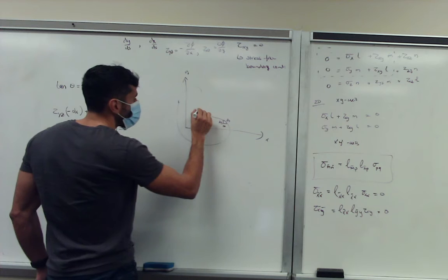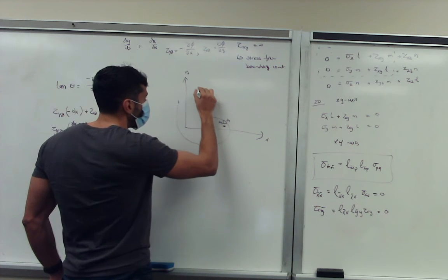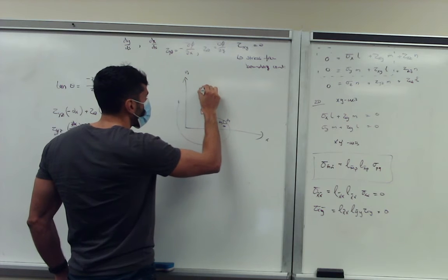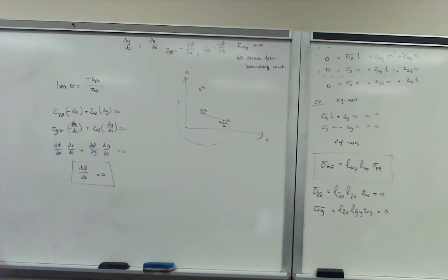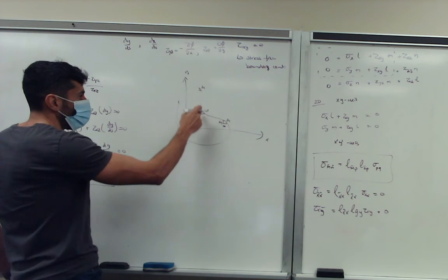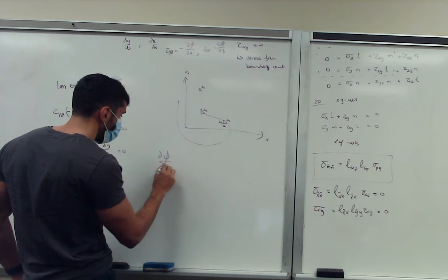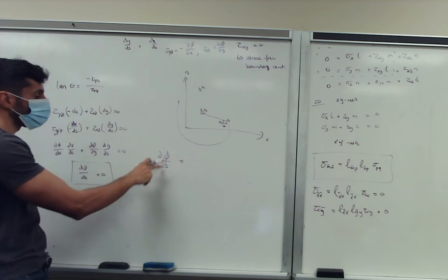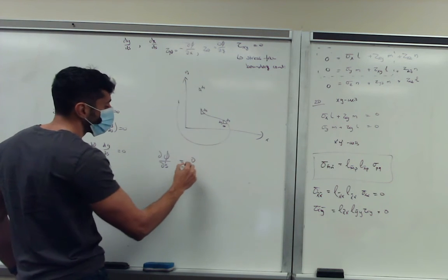In this section this path is ds here, and over here we have another ds. So what this means is that our Prandtl stress function phi along the boundary, so d phi/ds, meaning if we take the derivative with respect to the boundary, must be equal to 0.